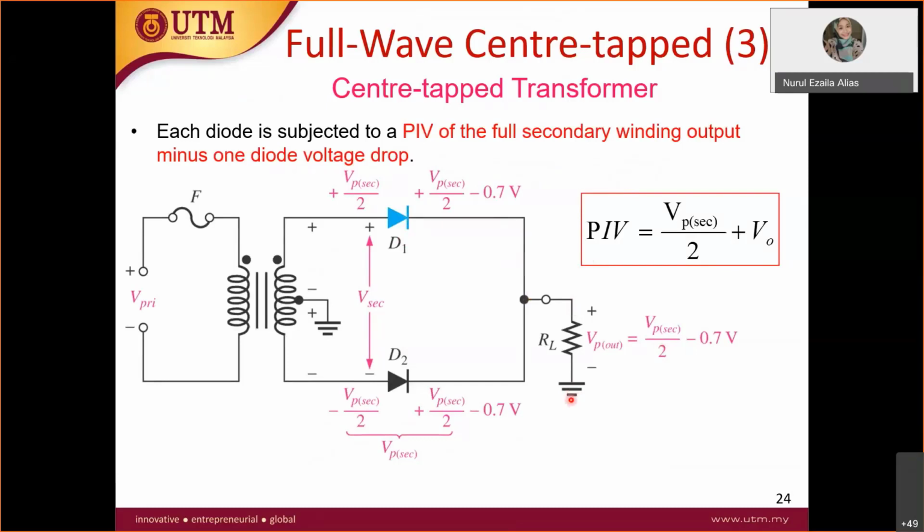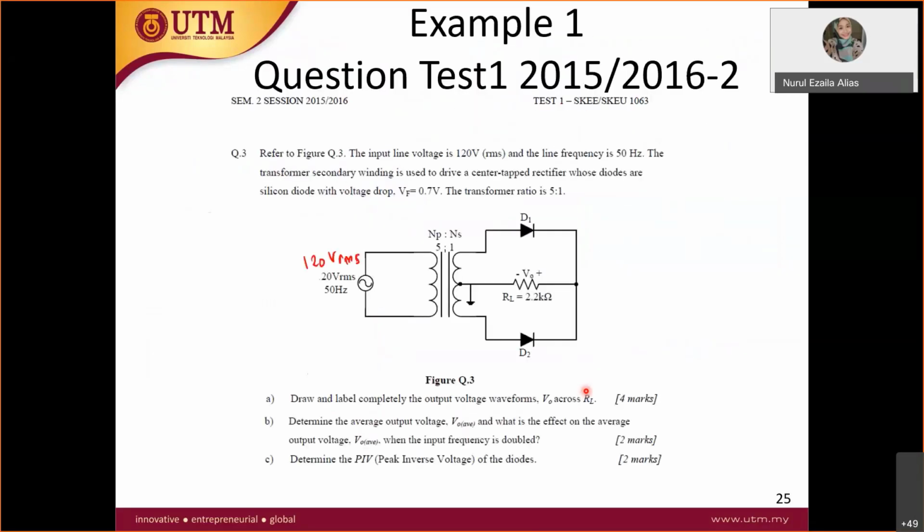Always your circuit will end at the ground. Your test will draw it the other way around, but still this side of the diode connects to RL, and the other RL, which is negative, goes to the ground, the same ground as the center tap.